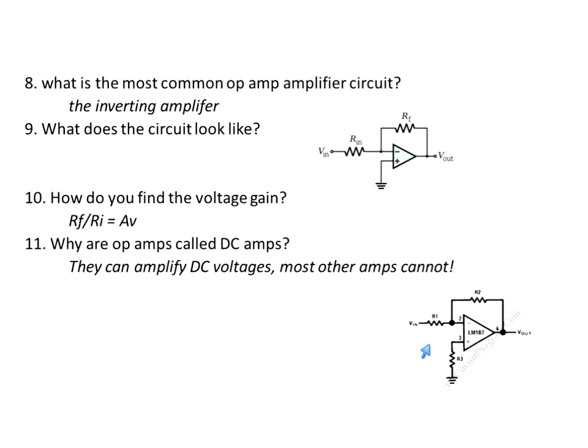A takeoff of the basic inverting amplifier is this one down here. It's exactly the same thing: Rn to the inverting terminal, and then Rf from the output back in. And they'll sometimes have this in here. This is called a compensation resistor. Do not worry about it. So you'll either see this or you'll see that. They're both inverting amplifiers.